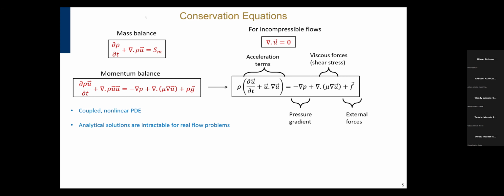Okay, so that ties in a bit with what Dr. Jude Bonsu has asked. If you have a multi-phase flow problem, for the mass balance you have to solve for each phase. If you are dealing with an Eulerian approach, you have to solve the mass balance for each phase. So you have two equations, but you know that the sum of the volume fractions in each control volume is equal to 1, depending on how you are treating that.